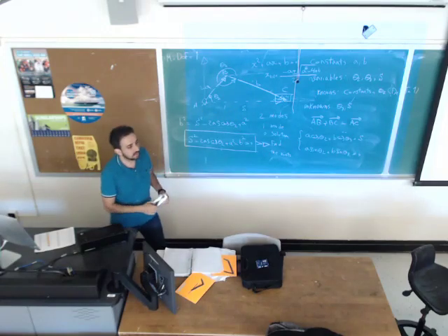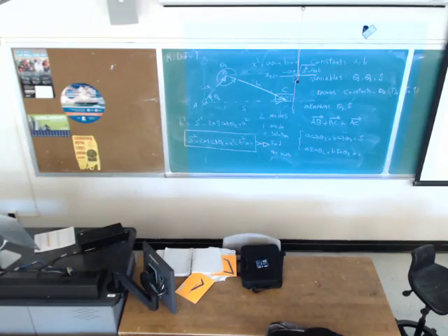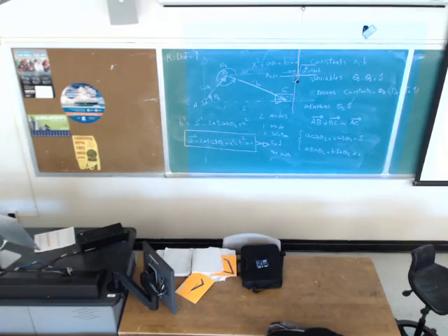Question: can't we get up to 4 angles from the cosine? You will get 2 angles from the cosine. Which one is the correct one? I'm saying can't we get up to 4, because S has 2 values? This is for one mode. If you get 2 modes, you plug in S1 here, the first mode. You find theta 3 and negative theta 3, and you find theta 3 and 180 minus theta 3 from the sine.